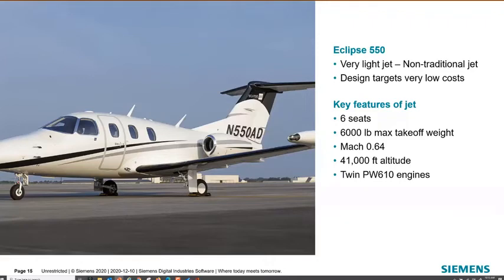Okay. So I worked with the Eclipse 550 jet aircraft, which, for those of you familiar with the aerospace industry, you probably know is a very light jet, fairly non-traditional from the standpoint of small jets, because it has 6 seats and is aimed at targeting the design space under 6,000 pounds to be able to fit in Part 23. It operates at a decent Mach number, Mach 0.64 at 41,000 feet, uses some of the smallest Pratt & Whitney engines that you can get, and really tries to target low operating costs for either the business jet crowd or owner-operator people.